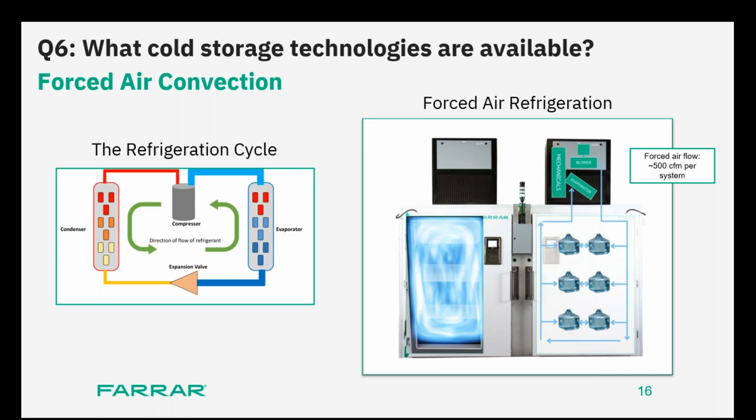Number two, obviously, as you're opening and closing the door, temperature excursion is something that's inevitable. But now think about it. The forced air convection would help you with this temperature recovery because it's no longer stagnant air. It's constantly pushing air, so you're recovering and reaching your set point temperature of -80 that much faster. So that's the benefit you get with forced air convection.